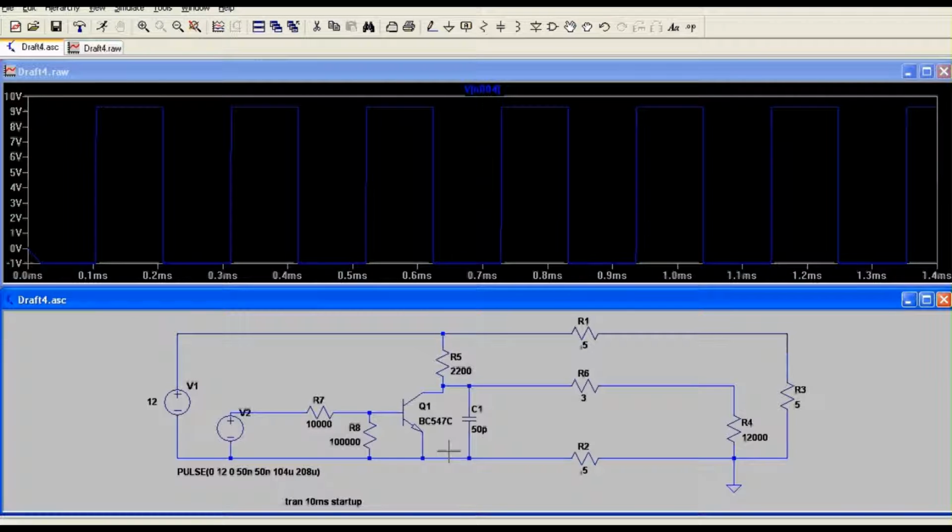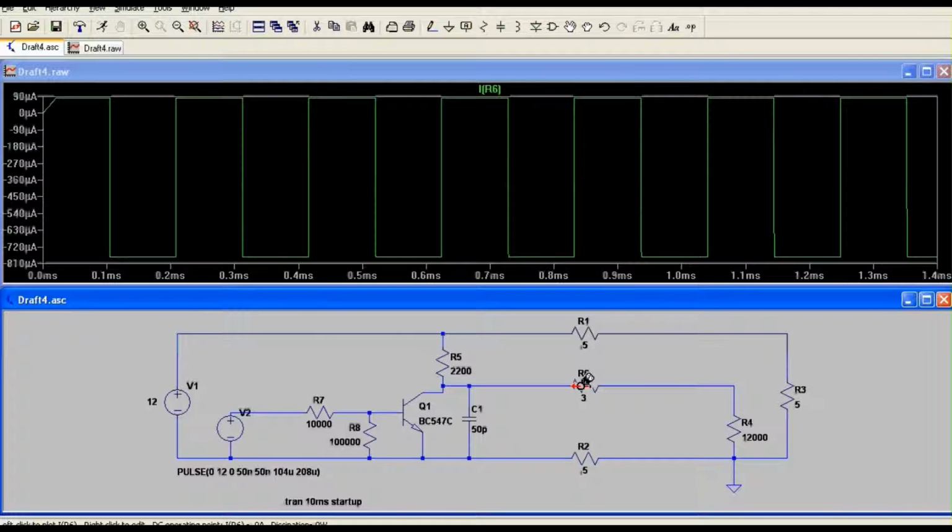The voltage that we're measuring here from this reference, this R4, the input into the silicon, doesn't represent a big load, so there's not a lot of current being pulled, and we can have a look at that. There's not a lot of current being pulled through this wire here to the silicon receiver, so there's not a big voltage drop across this wire for the signal.